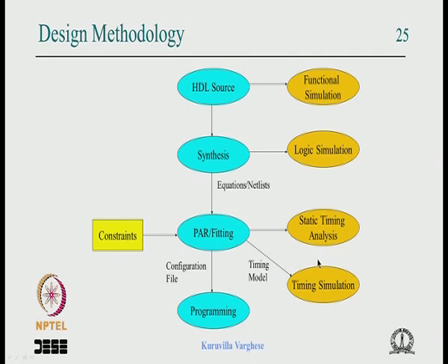What is available is a set of registers, combinational circuit, a set of registers, and it adds up all possible paths and shows the delay. Now it may make a mistake. It might report a path from one register to another register which is never used in the real circuit in real life. Because the controller is the one which is controlling the data path, maybe there are 4 source registers, some combinational circuit, and say 5 destination registers. The real operation of the circuit only involves a kind of one-to-one mapping.